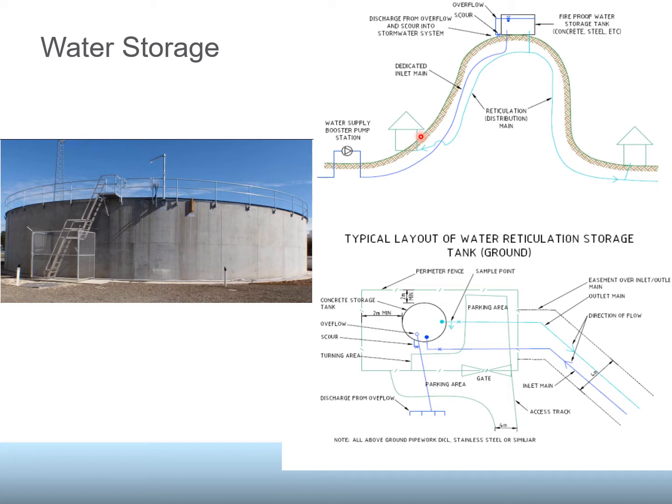So to provide water through gravity, it has to be either elevated if there is no topography to put the storage tank at the higher elevation, or if that is available, then you put this at the higher elevation in the area.